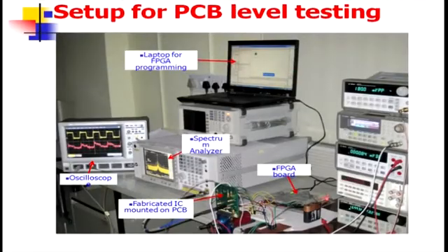And then coming into the testing part. So this is my old test lab. Now it has been changed completely. You can see yourself the spectrum coming from the spectrum analyzer, and you can use an FPGA board to control the bit pattern, to make a 6-bit or 8-bit pattern to switch the capacitor arrays and the control bits of your divider. So both can be programmed by this one, and this is the power supply and so on.